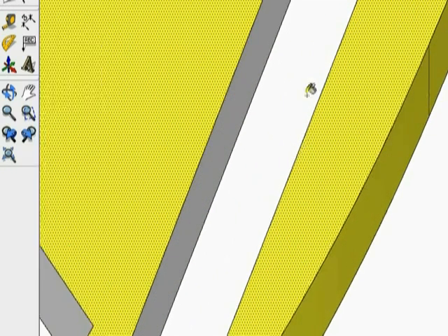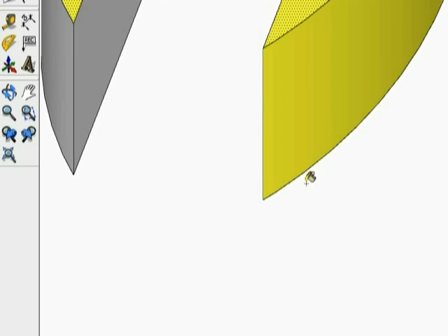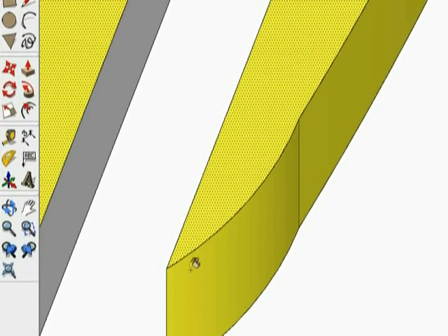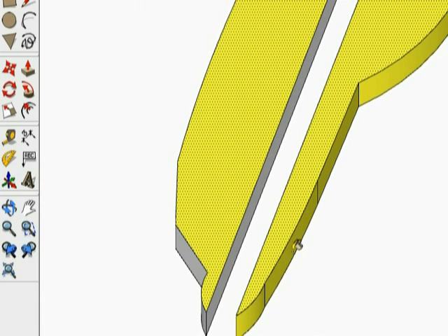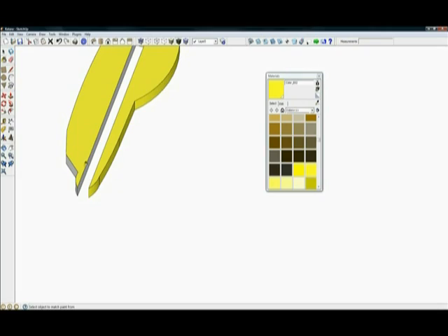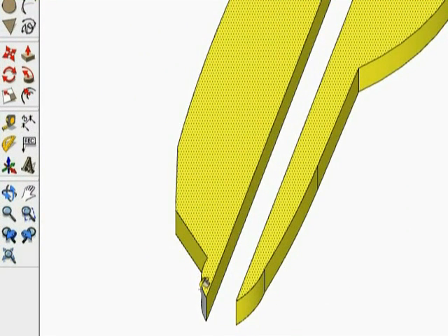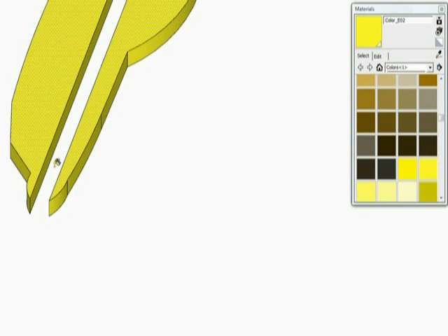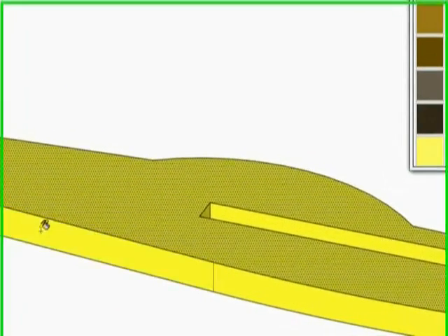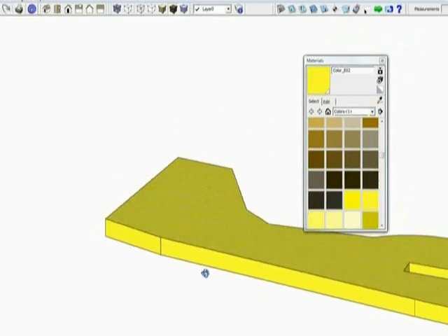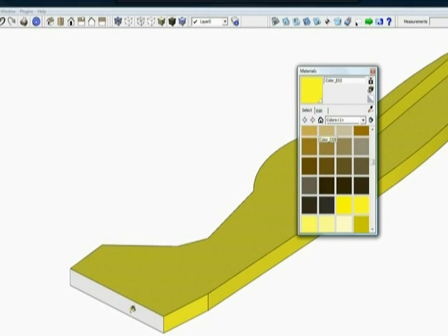Now, something that you may be wondering is, I've got some nice arcs here. How did I get those? Well, there's a way to do that using the Weld tool, because what it does is it unifies a bunch of different line segments into one smooth line segment. And we can talk about that later. But anyway, I just go through it. I paint all the sides. If I use my orbit tool to rotate around, and then I can click here again, and now I'm back to my paint bucket. Orbit by hitting the O, back to the paint bucket, which I think is B.